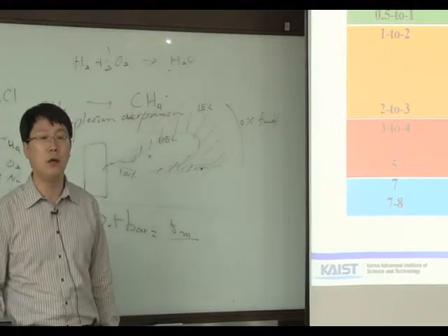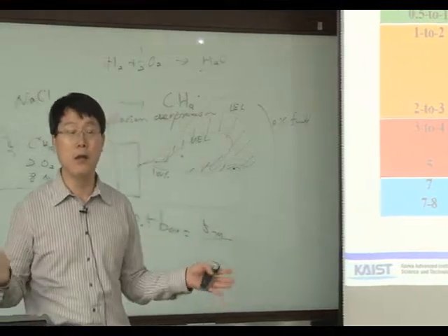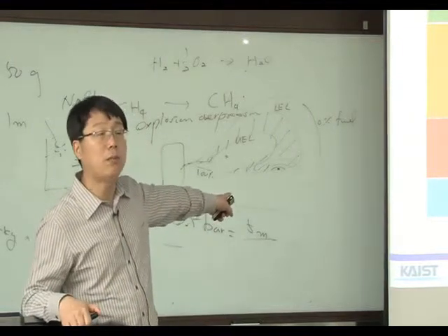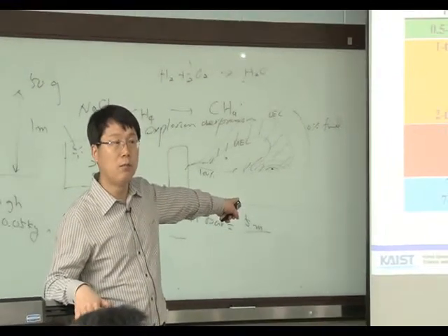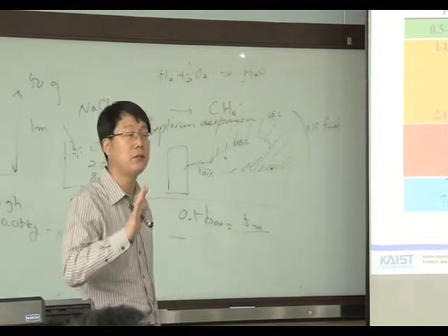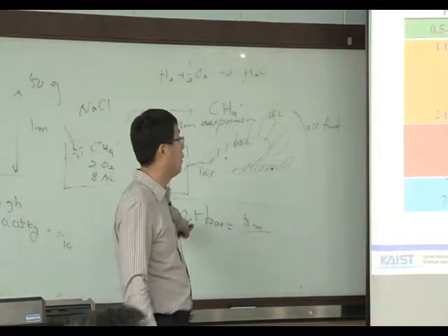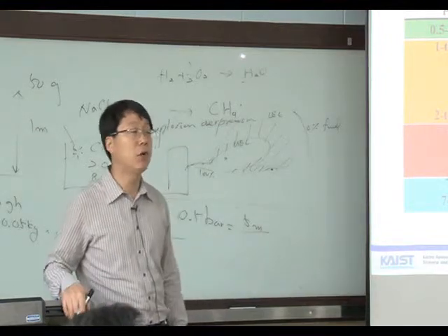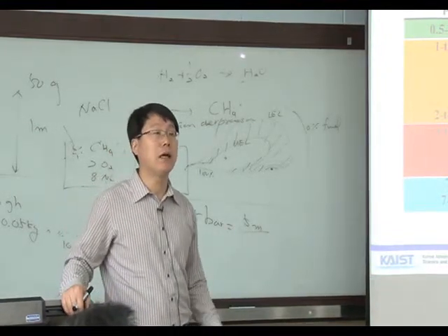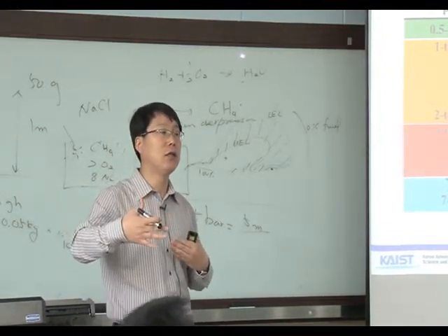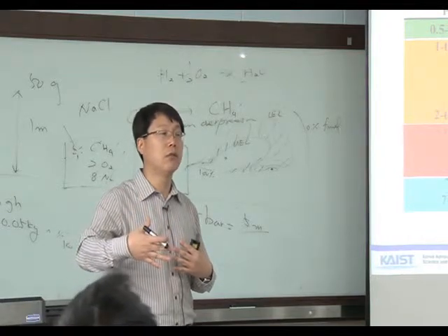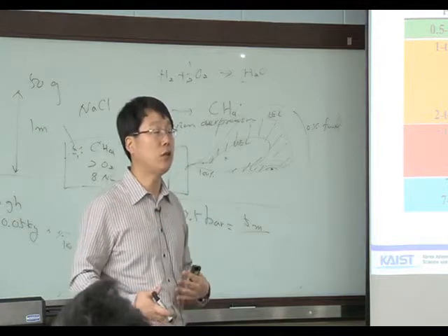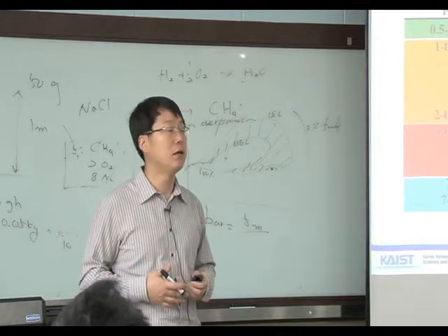The brick wall will never fail with the hydrostatic pressure of 5 meter. But the dynamic pressure, explosion dynamic pressure, can fail the brick wall. What I mean is that the magnitude is not important. What is important is whether the overpressure is sharp or not.